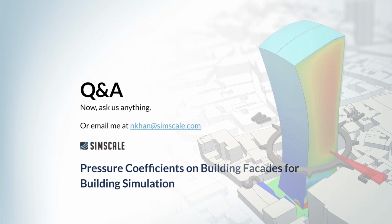Another question was, are these steady state results or transient? Just to clarify here, this is SimScale's pride, the Lattice Boltzmann solver. It is transient. We've obtained these average results by averaging over time. And all these transient results were run with a turbulence model called k-omega SST delayed detached eddy simulation, which is a hybrid model and highly regarded as a very accurate one.